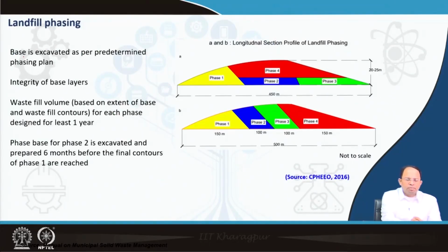So we have discussed that the base is excavated as per the predetermined phasing plan. So we have to decide on the phasing of that particular landfill site, and then accordingly the base has to be prepared. Because these phases are done not simultaneously but one after another, at the end of the day the bases have to be integrated so that there is no leakage between them. Because of the two phases, we have bases constructed at two different time periods, so there may be some gaps in between. That should be prevented. So the integrity of the base layer should be maintained.